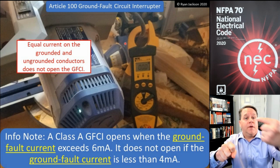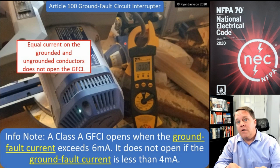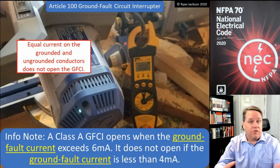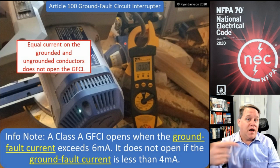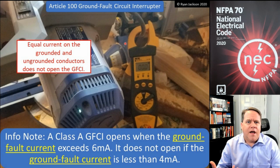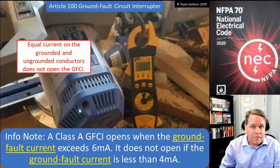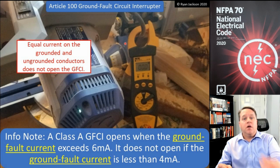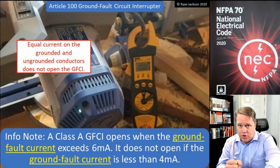So 10 amps is coming out, 10 amps is going back on the neutral. But some current is going to be going through me, right? Because I'm getting shocked because of the ground fault. So it's actually not 10 amps leaving the power source, it's 10 plus a few milliamps. Let's say it's 10 amps plus 10 milliamps, so 10.01 amps. That 0.01 amps is flowing through me. It's not going back on the neutral.